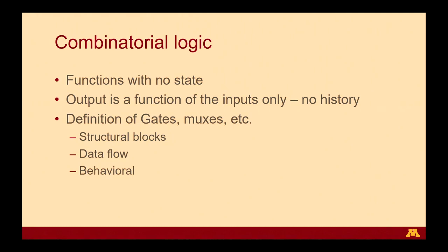Coming to the next slide, we are going to talk about the different types of hardware which you can synthesize using Verilog. This is not meant to be an exhaustive list, but just to give you a rough idea of the scope and capability. You can always try yourself to explore, design different modules, synthesize them, and see how Verilog synthesizes the code you write. For combinatorial logic, I wanted to show you the three ways you can design in Verilog. Namely, you can design it either as structural blocks, as a data flow model, or as a behavioral model.